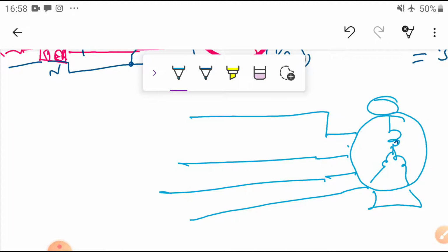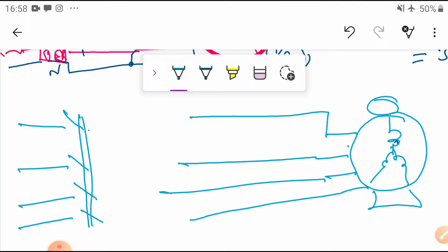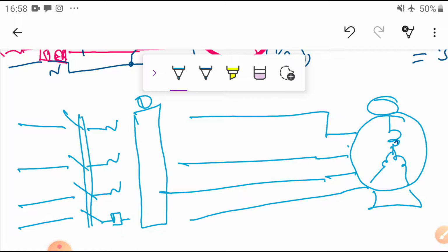Now similarly I am going to connect here R phase, Y phase and B phase and neutral. You can take the ICTPN switch, the fuse, and this is a link. Now I connected one starter, an auto transformer, or you can connect a star delta, automatic star delta starter. If the motor capacity is less than 5 HP, you can use the DOL starter also, for 3 phase.